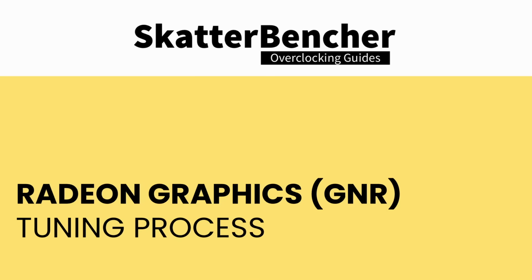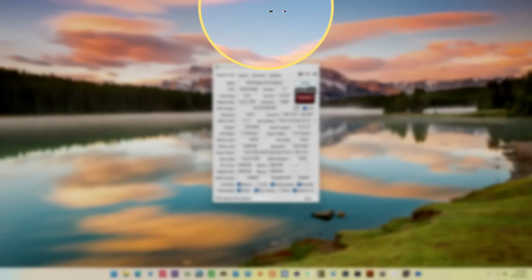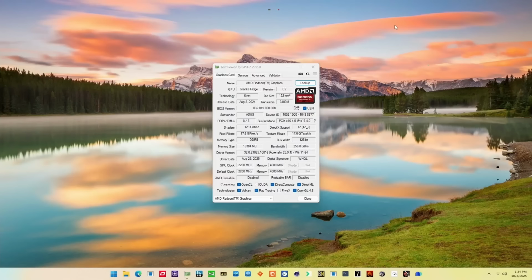If the theory feels overwhelming, then I have great news. Actually doing the overclocking is much simpler. In fact, it's just a matter of running up the target clock until you see signs of instability. I found that the earliest sign of instability is getting artifacts on desktop. I got these around 2.9 GHz, so I settled for a GPU clock frequency of 2.8 GHz.